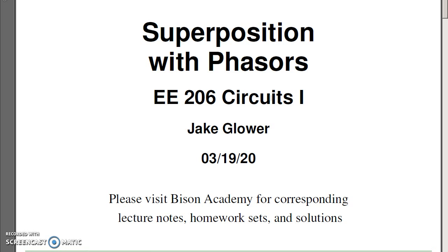Now that we have phasors, we're able to analyze AC circuits, or circuits with AC inputs. Let's go back to superposition. Prior with DC, we were showing that if you have a circuit with two separate inputs, you can treat that as two separate problems. The total response will be the sum of the two. Back at DC, that was rather silly, because you might as well just analyze this whole circuit at once.